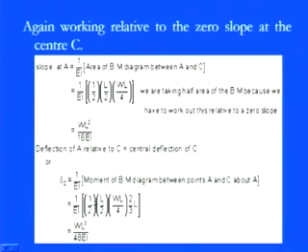This is the total; all those elements are calculating the area, and then you see this Y bar, which is nothing but equal to 2/3 of the length. So for the entire region of this beam, where you see the bending moment diagram like that, the deflection is nothing but equal to WL cube by 48 EI. We also calculated the same thing using the direct integration method.